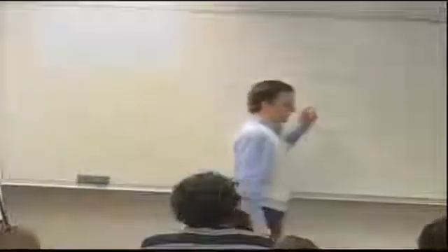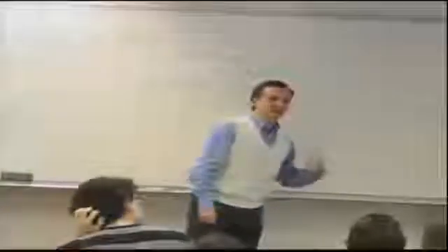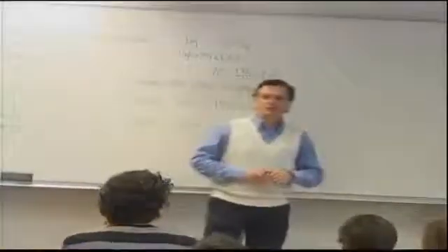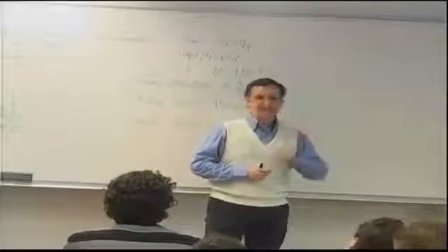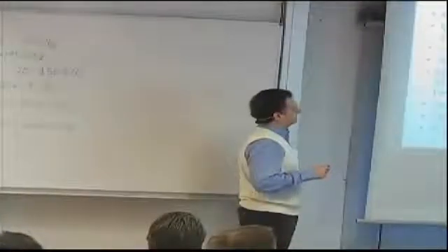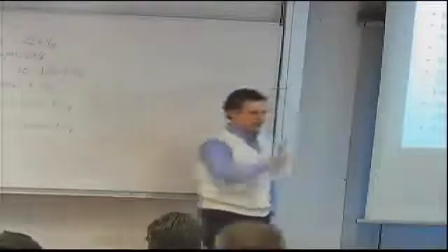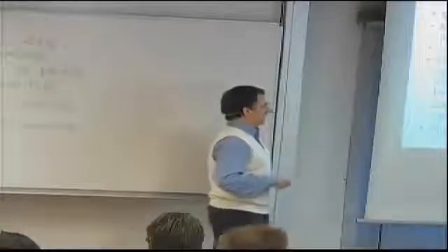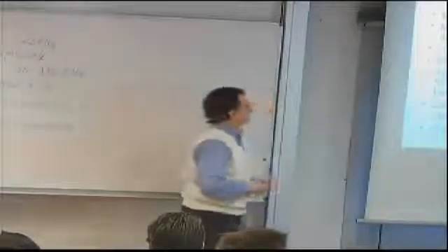So on the one hand, if you are inefficient in your design, then people will tell you, you are not good enough, we don't want these kind of people because we're trying to save weight. On the other, if you are smartly inefficient in your design, you can make a lot of money. So cost is a big deal, therefore, and it can range, again, as I was saying last time, from the recurring, which is every time you make it, how much it costs you, labor hours, wear and tear of equipment. Non-recurring, which is the equipment, tooling, molds, and so on.